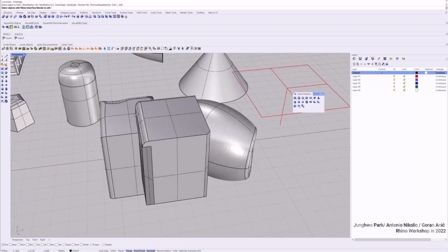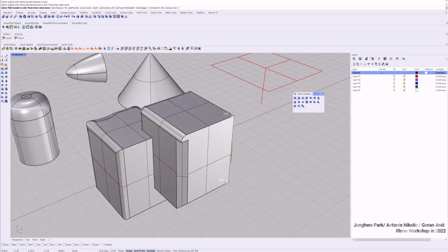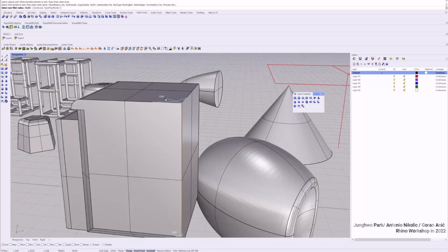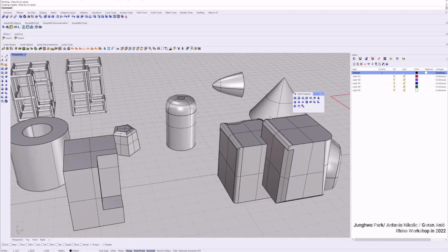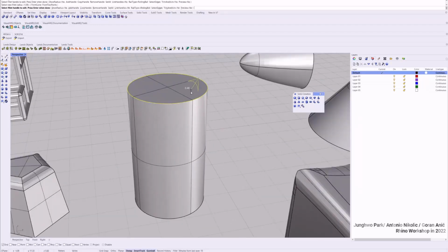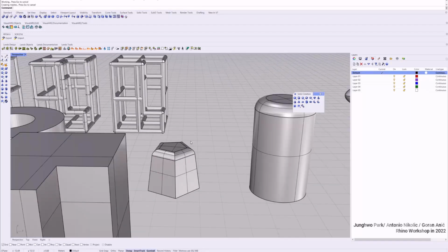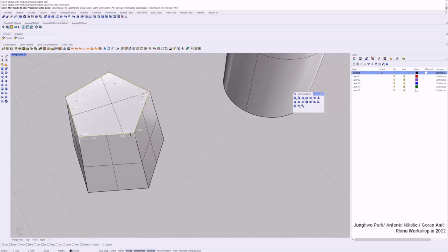You can also edit fillet edge. So when you click that edit fillet edge option for your solid, then you can see there is an editing option, and you can finish the command. We can go back, click there, and instead of that I can change to this, and I can edit. So as long as it's a fillet edge, it recognizes, and you can change the value of that.